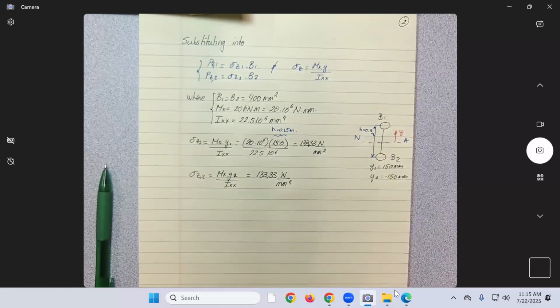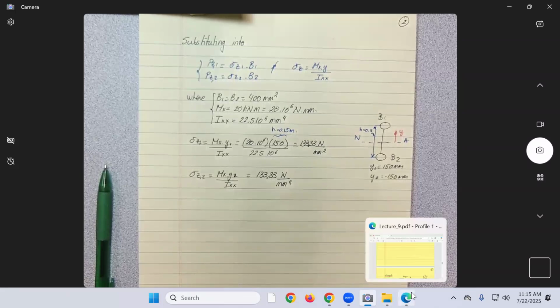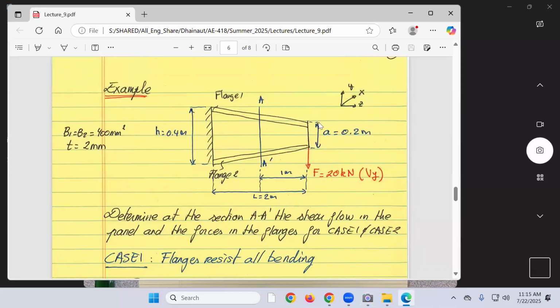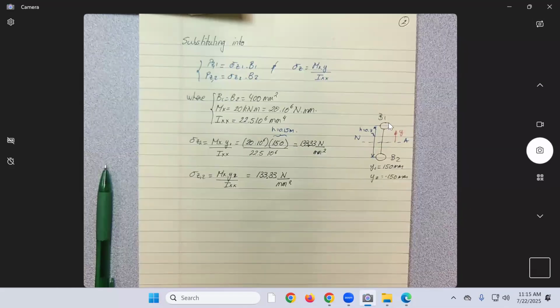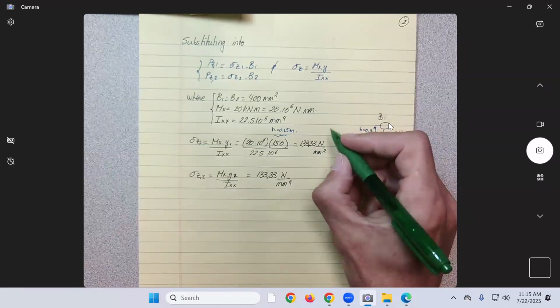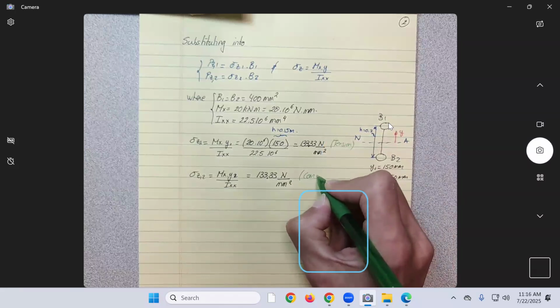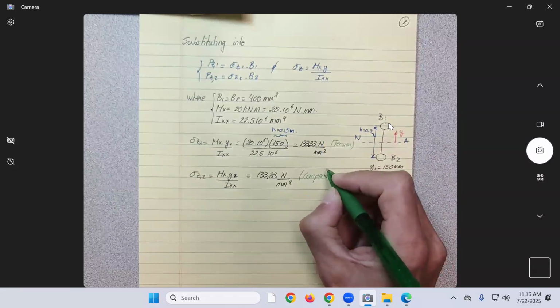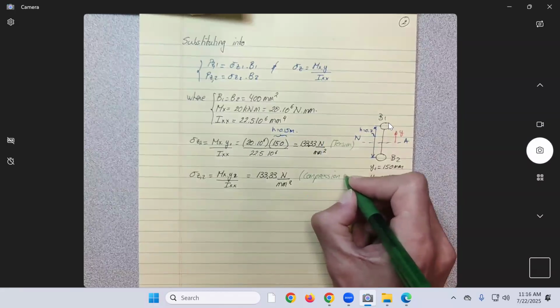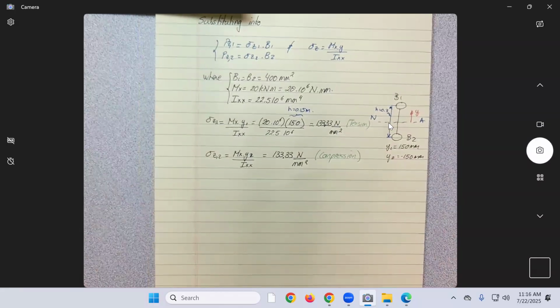All right, here let's be careful. So this is our problem that we are solving. Look here at the board. If you pull this down, this side will be in tension, this one will be in compression. That's why I don't pay that much attention to the signs, but if you want, the top side will be in tension, so you can put here tension, or leave a positive value, and here put a negative value and put compression. I rather write tension or compression.